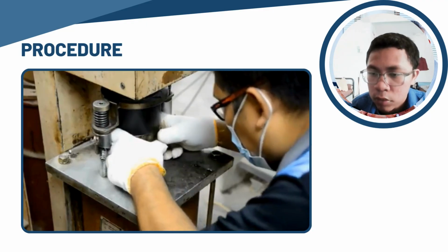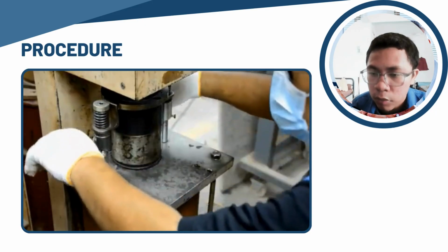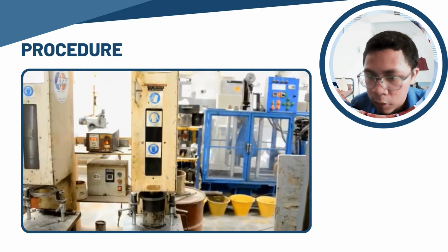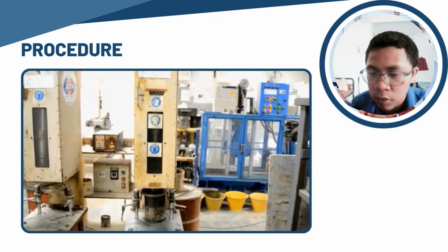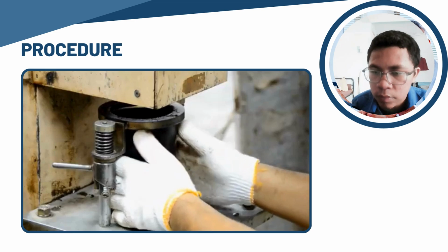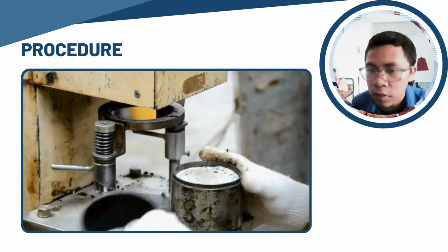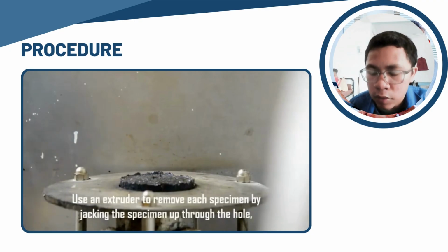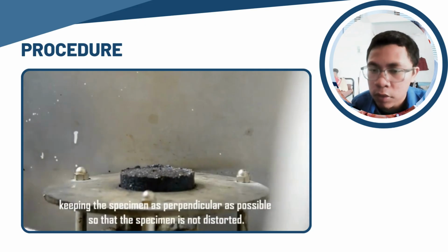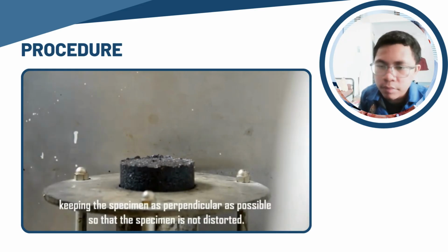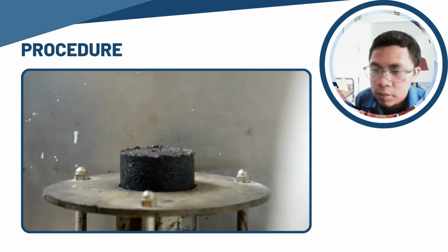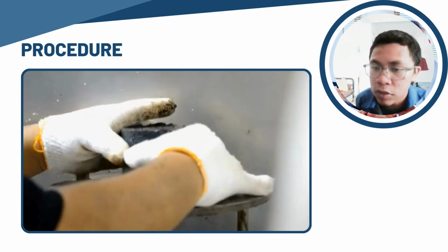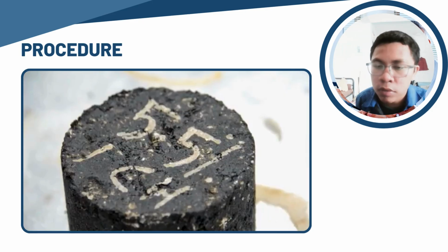About 1,200 grams of blended aggregate sand and filler is prepared in a container to produce a Marshall specimen. Oven dry the aggregate at 115 Celsius for at least 4 hours. Heat the asphalt at the same temperature or at mixing temperature, which is about 114 Celsius.